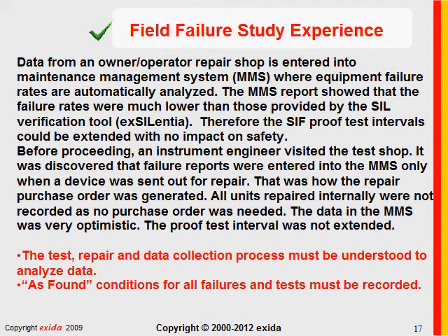However, before proceeding, the instrument engineer visited the test shop. Remember, I said that someone must understand data collection procedures before having confidence in the data. It was discovered that failure reports were entered into the MMS system only when a device was sent out for repair, because that's how the repair purchase order was generated. All the units that were repaired internally were not recorded as failures because no purchase order was needed. That's obvious.